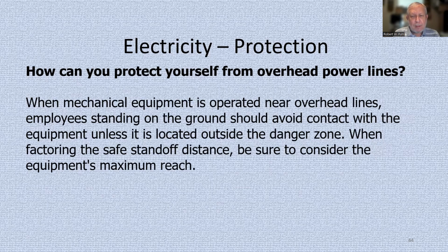When mechanical equipment is operated near overhead lines, employees standing on the ground should avoid contact with the equipment unless it is located outside the danger zone. When factoring the safe standoff distance, be sure to consider the equipment's maximum reach.